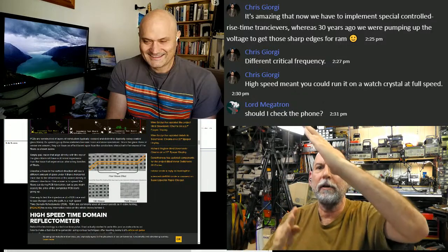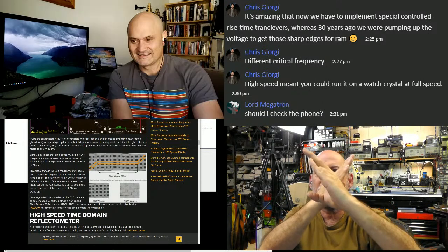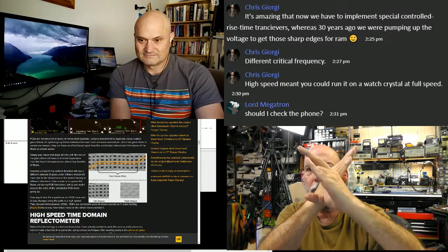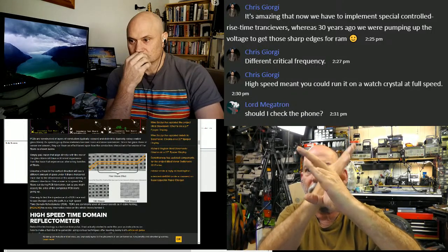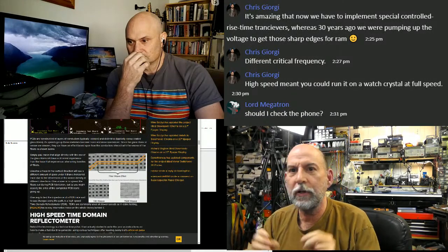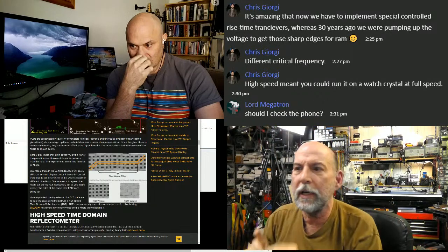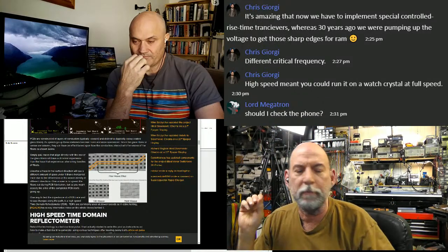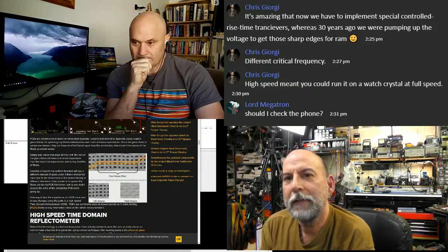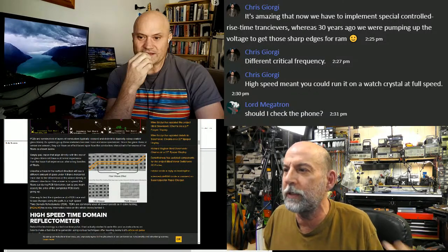If one goes high at one time and the other one goes low, that's noisy, but if we can get them both to cross right at the same time. So there's a theory that says, well, we don't want them both to have noise at the same time. We'd rather have just one be noisy and then have the other one be noisy randomly. And so there's a school of thought that says run your differential traces differently rather than next to each other, as long as they're the same length. Yeah, and now, would I do that? No, I would run them next to each other because I'm not going to take a chance.